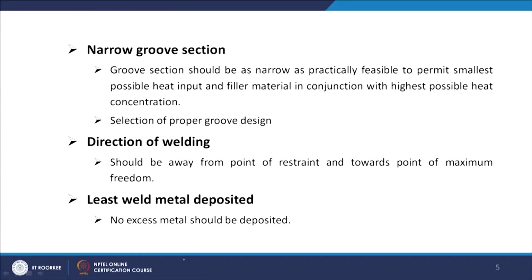Next comes the narrow groove section. The groove section, as you see, should be as narrow as practically feasible to permit the smallest possible heat input and filler material, in conjunction with the highest possible heat concentration for the welding method.